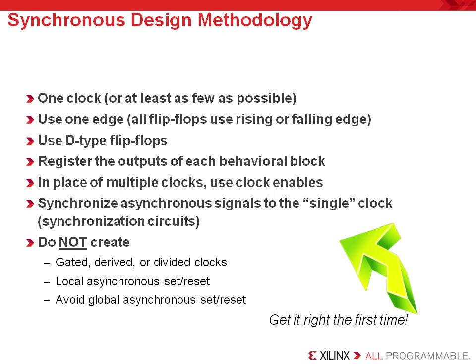Likewise, don't gate, derive, or divide clocks manually. Use a DCM or a PLL resource for that purpose. Or build it with a clock enable. Deriving clocks with LUTs and registers almost always builds a glitch into the system.